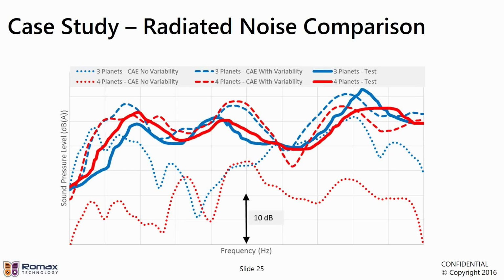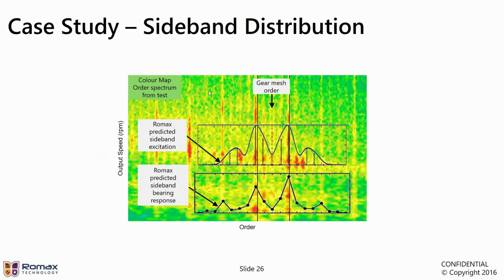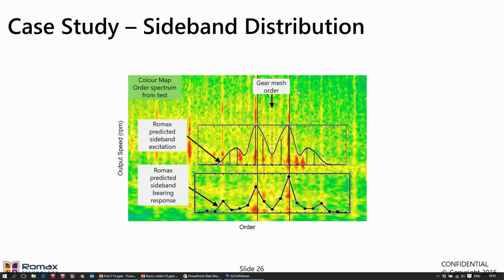The other question is, how much contribution of type 3 coordinate transformation in your case study dynamic response compared with type 1? Well, it really is a mixture. The majority of the sideband behavior comes from the type 1, because those are the ones that add additional energy in. The type 3 sidebands just move energy around between different sidebands and adjacent sidebands. So some of the sideband energy largely comes from the type 1, but they will be adjusted and moved around by the type 3. So if we go back to this figure, we would expect to see some energy here